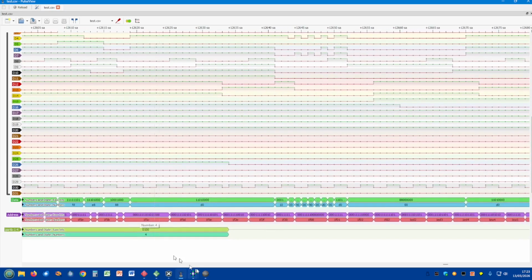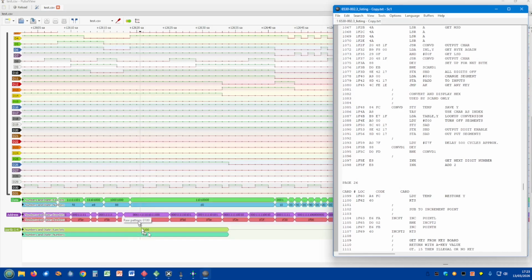So at this point here we should be doing 2 cycles for that instruction, which should end in there. And now we've got 1F5D, that should have FD. So at this point here we should have FD coming out onto the bus to be strobed in. And we just got D0 again, which is branch if not equal again. So it's going to try and branch to that location because it's going to read that in instead of FD.